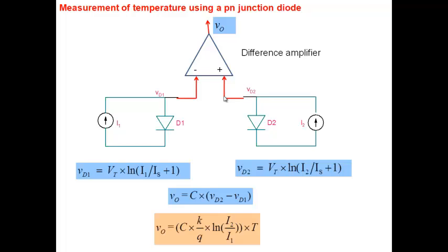On silicon, you can only build very low values of capacitors, in picofarads. You can't build nanofarads of capacitance. Which means that the whole circuit, you will find difficult to integrate on silicon. Those capacitors will have to be external. And when something becomes external, it becomes bulky. It's not as compact. So that's the price that you may end up paying.